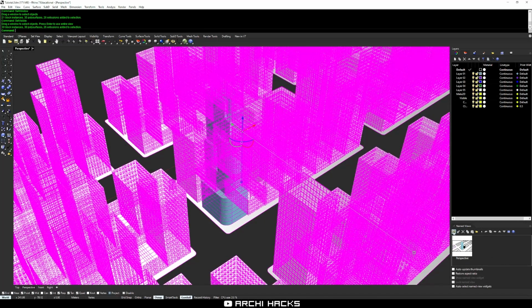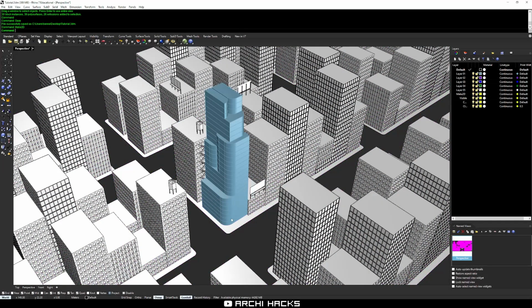Okay, I'm going to save this view and call it Perspective so that we can always come back to this later. Okay, before we go, I'm going to Make2D, but this can sometimes take a really long time. So you might want to save your project before you proceed. So I'm going to type in Save. One thing that might be really helpful is to make sure that your project is on a separate layer so that it'll be easier to highlight this in a bit.